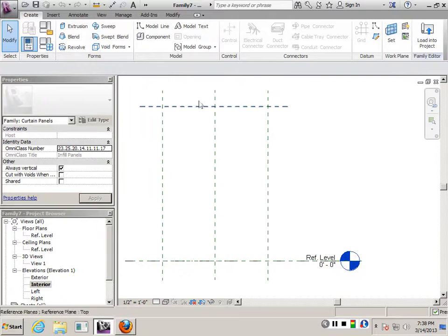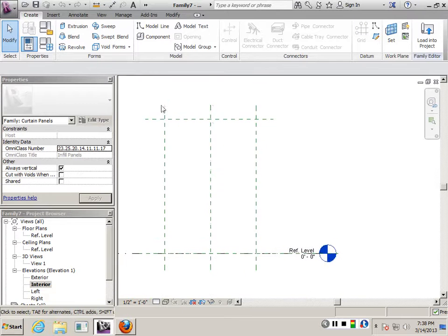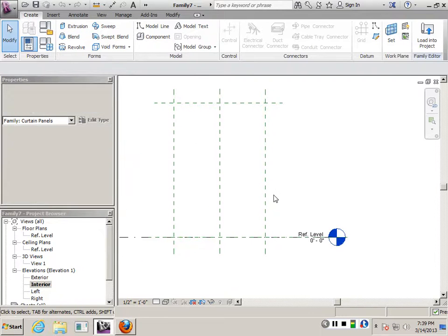And what I want to do is define an inner rectangle that is constrained by the width and the height of this panel. Okay? And similar to the previous example, I'm going to define them as reporting parameters, so we don't have to change them. So they will be generic models. So I want to create first, let's go ahead and create the height and the width parameters.